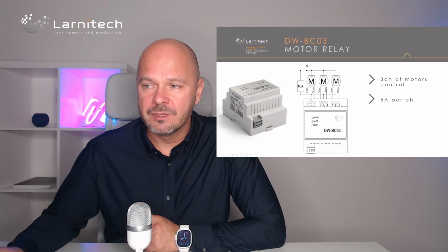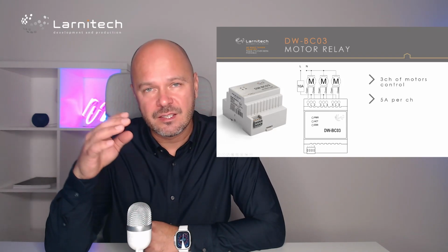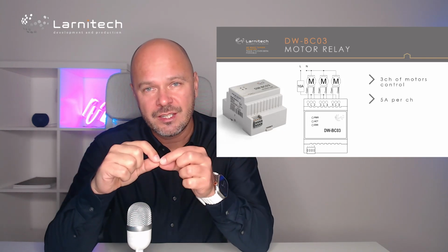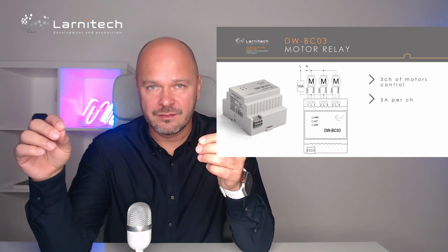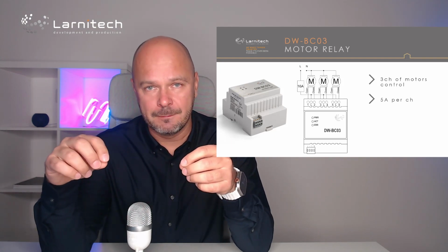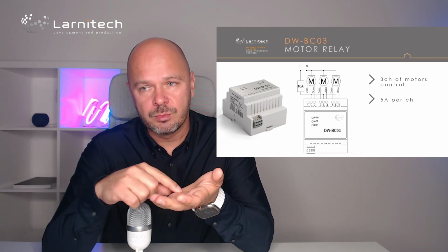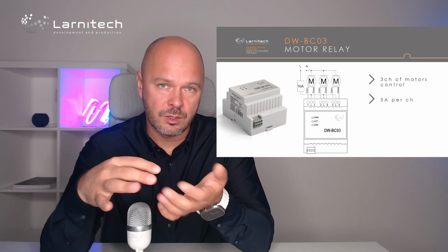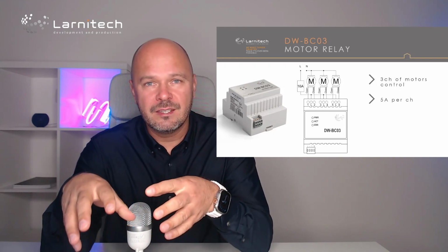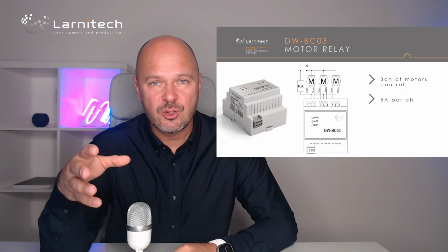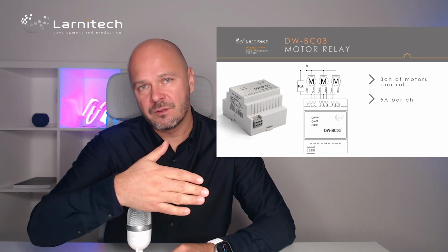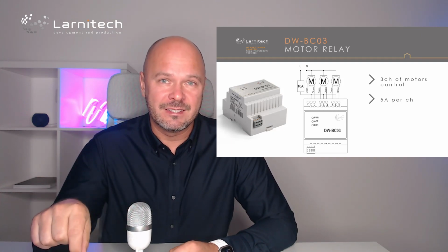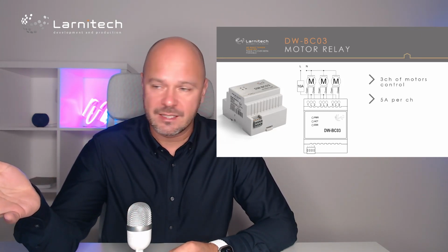So you will be able to test open and close the blind, and it will record the time which is needed to open and the time which is needed to close automatically. So you will be able to open like 30%, open 40% blinds, and so on. With a normal relay you can also do this, but you will need to enter the time of the motor to open and the time of the motor to close by hand. And here it is done automatically.